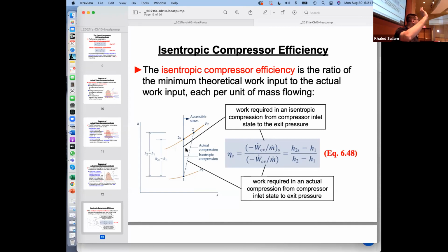So the compressor will just keep pushing until you reach the condenser pressure. That's the delivery. You need to deliver to that pressure, otherwise the flow will not leave the compressor, right? But it can go the short route if it's isentropic and take less work, or it can go the long route because of all the irreversibility and take a lot of work to actually get there. Okay.